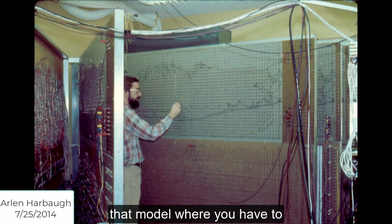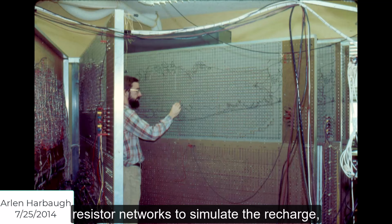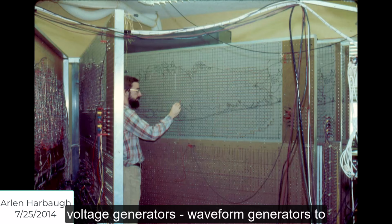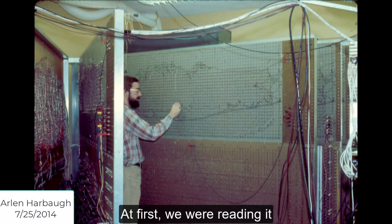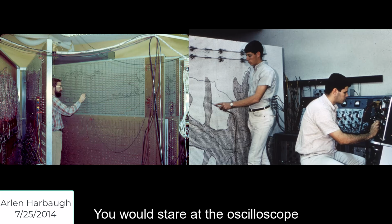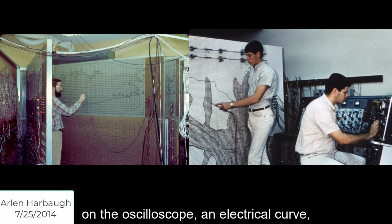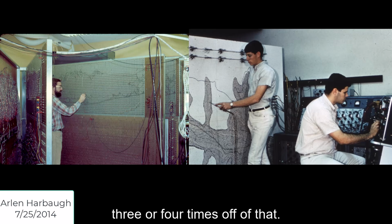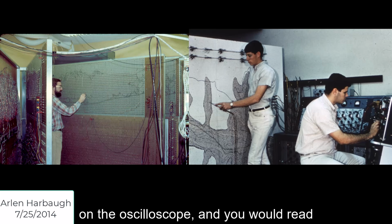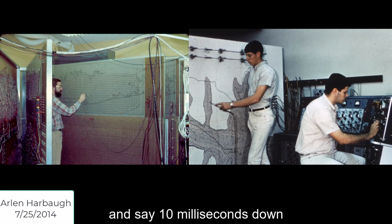operating that model, where you have to add the stresses to it, put in resistor networks to simulate the recharge and wells and that sort of thing, and set up all these voltage generators, waveform generators to vary these stresses with time. And then at first we were reading it with an oscilloscope, and you would stare at the oscilloscope and there would be an electrical curve, and we would be trying to read 3 or 4 times off of that. There was a scale on the oscilloscope, and you'd read the time at the beginning of the stress and say, 10 milliseconds down and 20 milliseconds down.